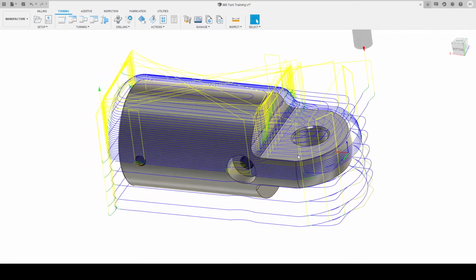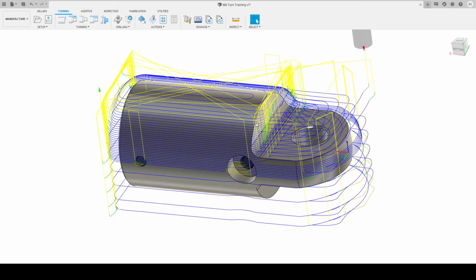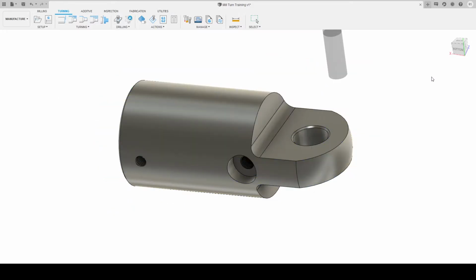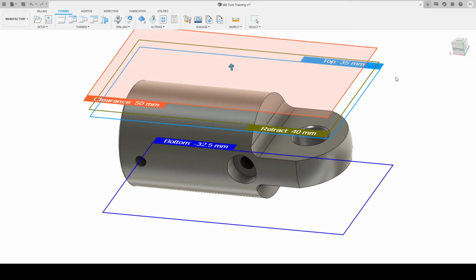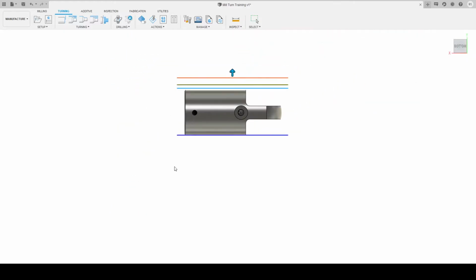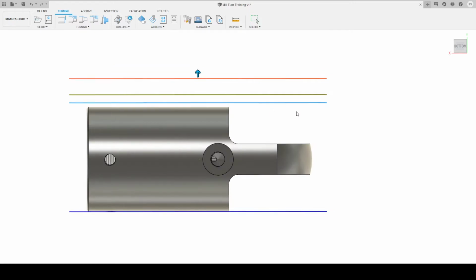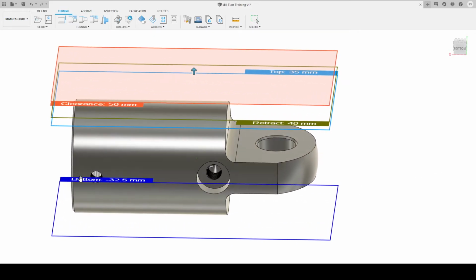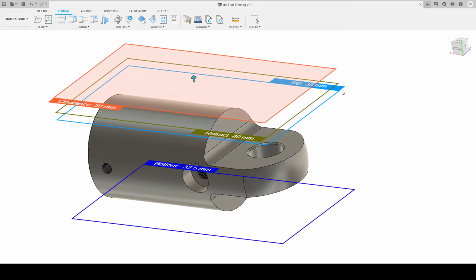So now what we do is start defining our toolpath a little bit more. So we can go into adaptive and edit that one. And a bit similar to the turning toolpath, when you're milling, the toolpath is looking from the bottom height to the top height. So it's going to machine everything from this bottom height here to this top height.